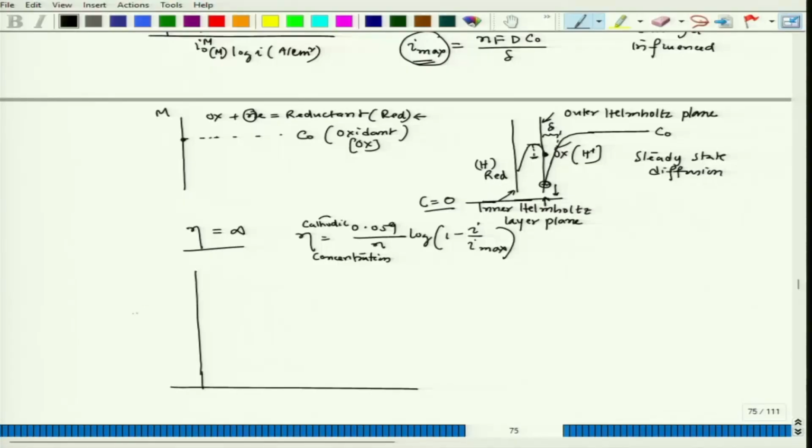So, that time the system would be considered a concentration controlled corrosion process. So, this is E volt versus log I ampere per centimeter square. Now, if I try to plot this for the cathodic process, initially it will be the activation part, and then we get concentration polarization. So, this is nothing but I max. Okay. So, this will be a typical plot.